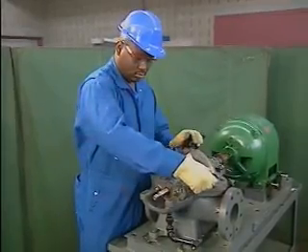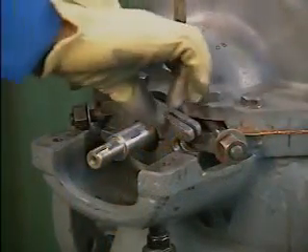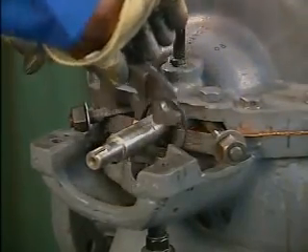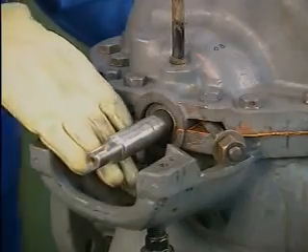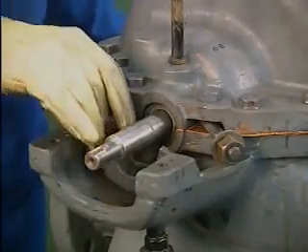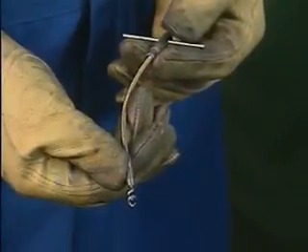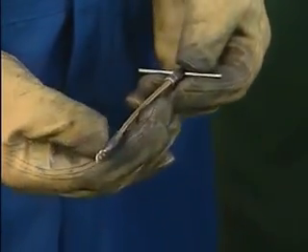The mechanic's first step is to remove the nuts that hold the gland follower in place. This pump has a two-piece gland follower that allows it to be removed from the shaft. If an application has a single-piece gland follower that cannot be completely removed, the gland follower should be tied out of the way along the shaft. To remove the old packing, the mechanic uses a tool specially designed for this task called a packing puller.